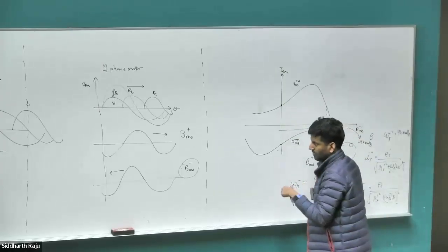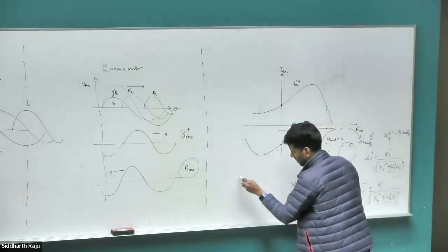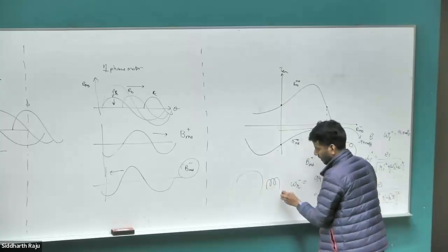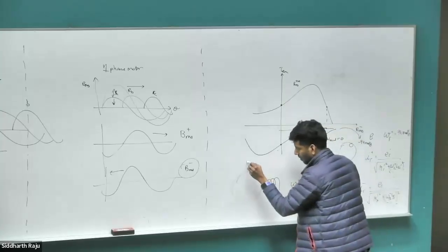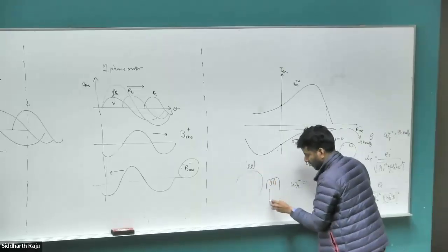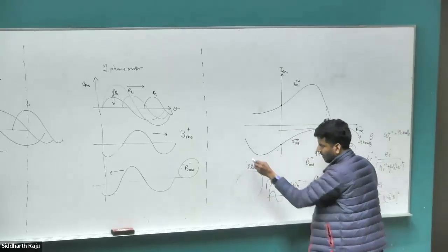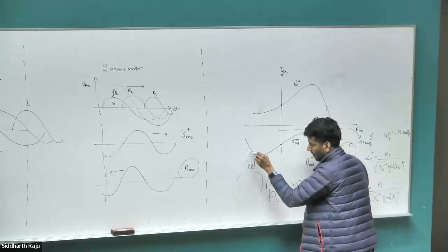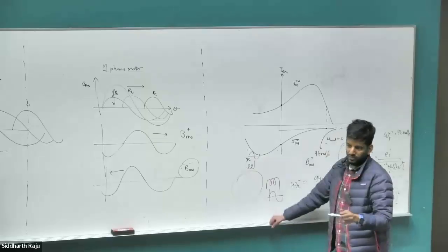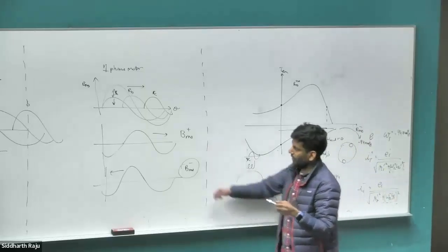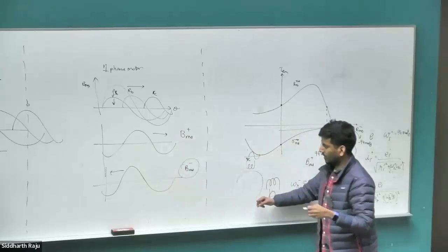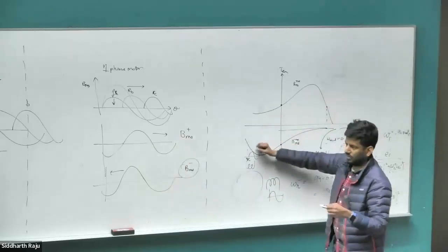So what they do in a one-phase induction motor, like the ones you have in your fans, is you have a stator winding, just one coil, but then they have another coil 90 degrees away. And if you are able to create a sine wave here for the voltage and phase shift the second coil's sine wave by an angle of 90 degrees, then you create a two-phase motor which has a rotating magnetic field only in the positive direction or in the negative direction, as you have seen before. And that will end up creating a sustained torque just in one direction alone, not the other one.